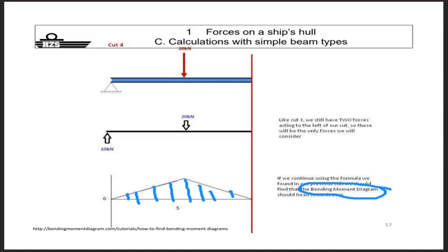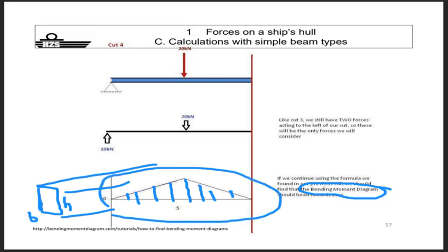And those stress levels should not be higher than certain limits, because the calculation is a bit more difficult than just calculating the bending moment. Calculating bending moments is easier than calculating stresses. Naval architects make your life easy. So suppose now your beam has the shape here of this B, H, a certain breadth and a certain height. And that is the profile of your beam. Your beam has this bending moment exposed to it. What are the stresses in those beams?